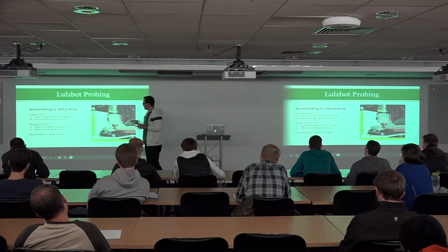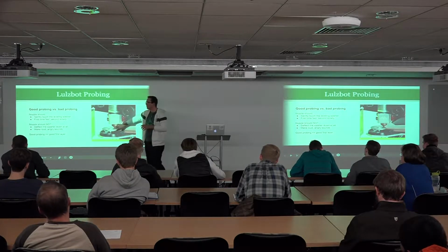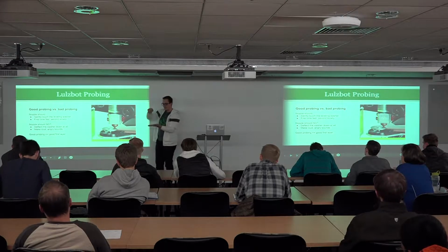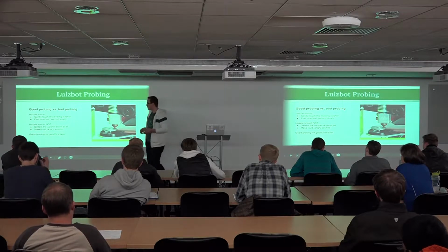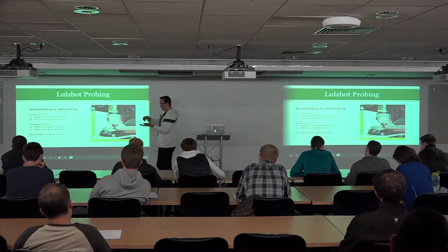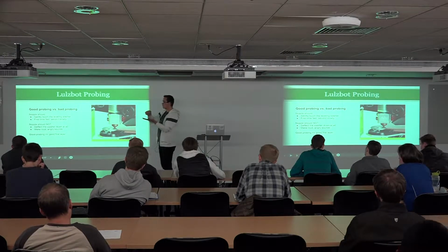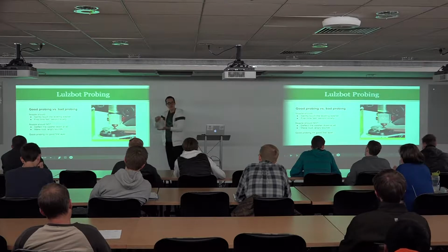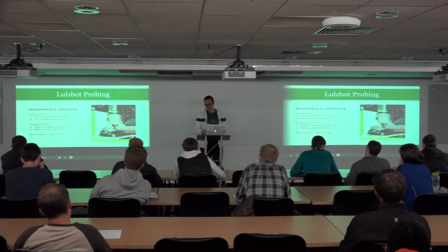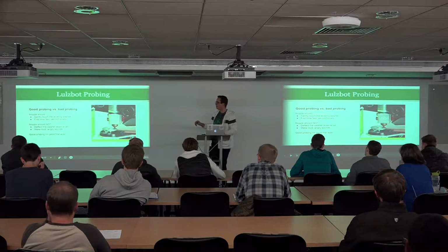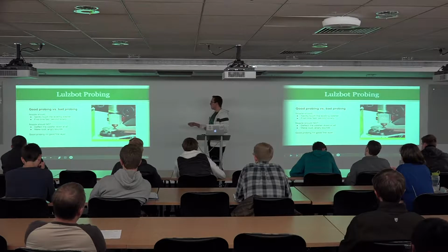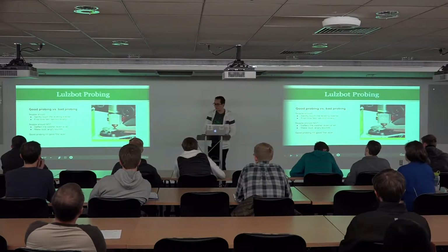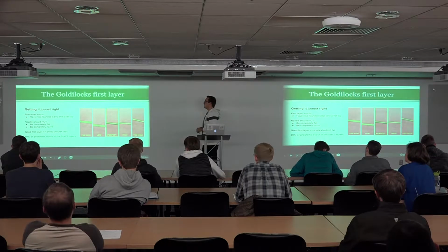And so it's up to the user. This is kind of the only thing you really need to watch, is that it comes down and touches the washer very gently, and then comes up and touches off on the other washers. It touches each one twice. It shouldn't press those washers down at all. If you see the washers deflect, or you hear nasty grinding noises, then that's a problem. And then you can just turn the printer off, turn it back on, and hit print again. We've got little wipers around to wipe those nozzles off if you see any plastic left on it.